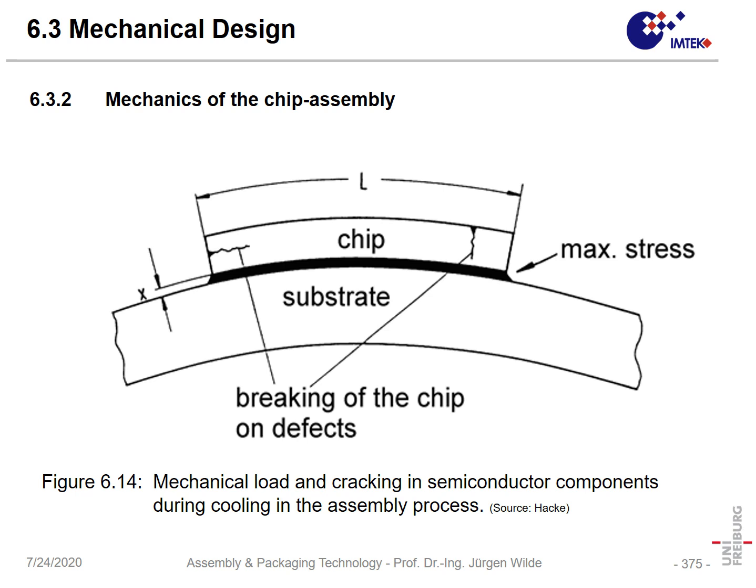Some of the cracks come from the top side. The reason is that here we have tensile stress. And for a brittle material, tensile stresses are worse than compressive stresses. So you can imagine you cannot open a crack by compression.